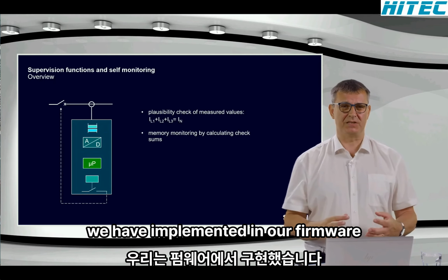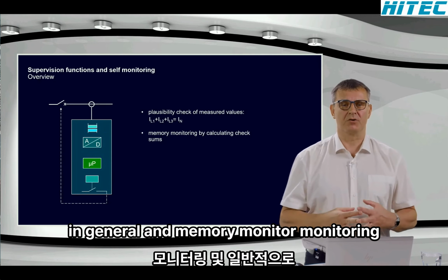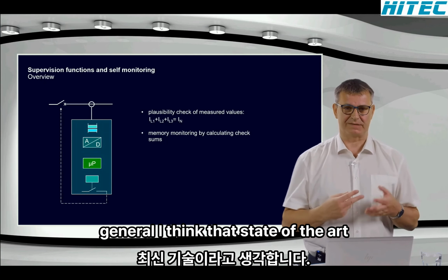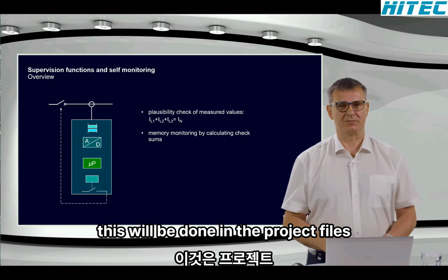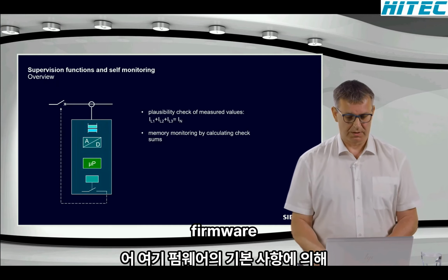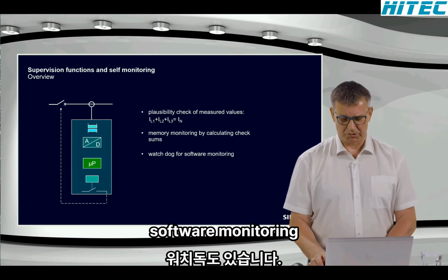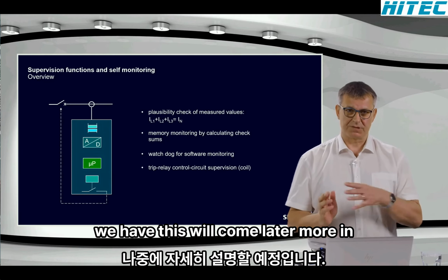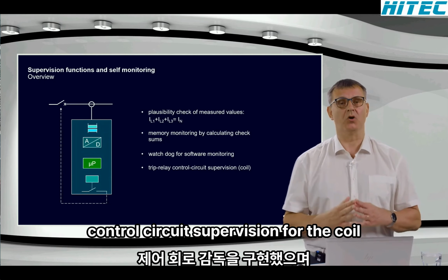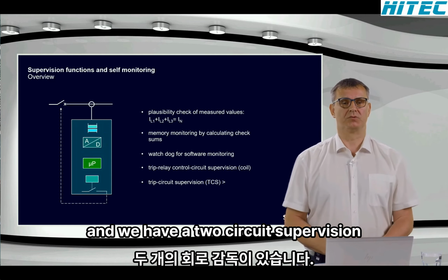We have implemented in our firmware basics, in general, a memory monitoring and a calculating of checksums. I think that's state of the art. This will be done in SIPROTEC 5 really by the basics of our firmware. We have also, of course, watchdogs for software monitoring. This will come later more in detail: we have implemented a trip control circuit supervision for the coil, and we have a trip circuit supervision also implemented.